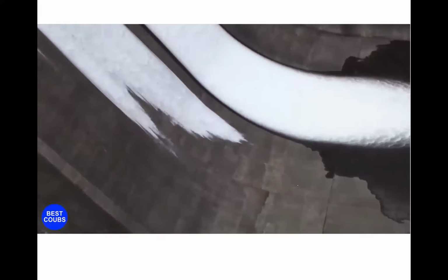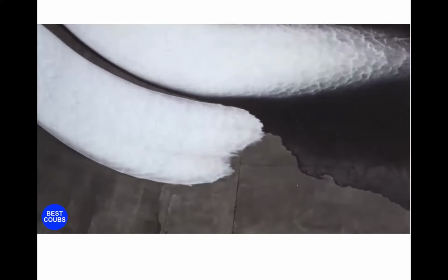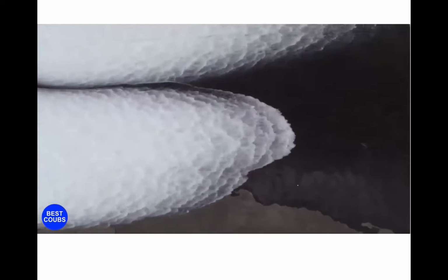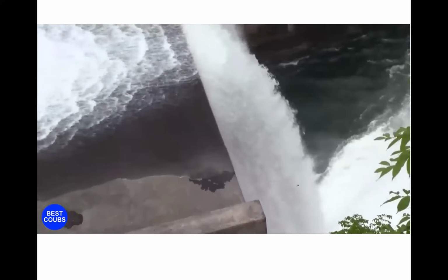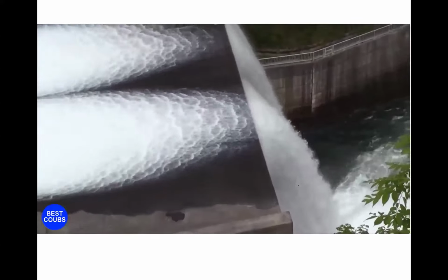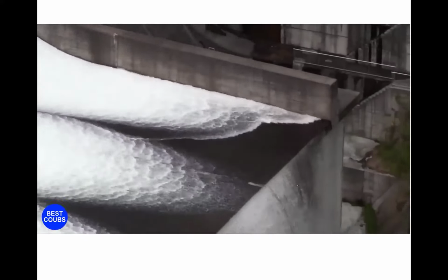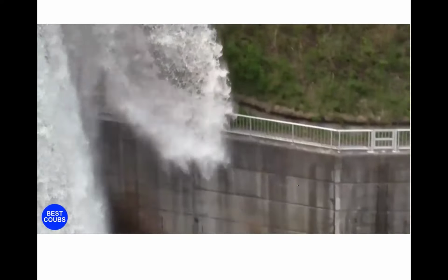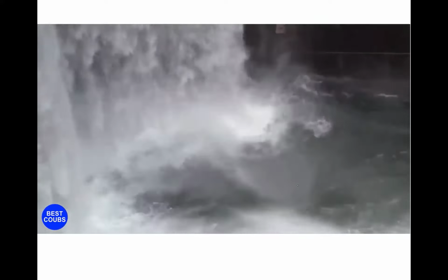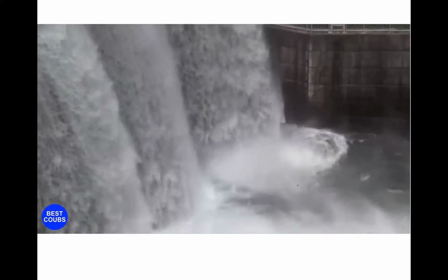Yeah, this is another spillway. They're opening the gates and discharging onto the chute, and then farther downstream. You see a lot of these structures have a combination of different discharge type facilities and structures. That's common for different purposes, depending on what you want to do with the flow and what the purposes could be. Different combinations of different components for discharge.